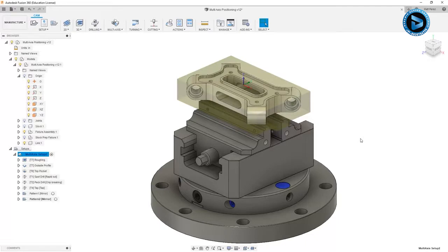So while so far we've machined from the top and then did our multi-axis positioning around the side, we could have done this on 2 separate machines utilizing a 4th axis. But with a 5th axis machine, we're able to do all of these operations without having to remove the part at all. This is a great time for us to save before we move on to any more operations, so make sure that your file is saved, and then you can move on to the next step.